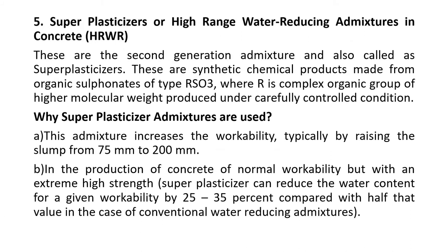Superplasticizers or high-range water-reducing admixtures in concrete. These are the second-generation admixtures, also called superplasticizers. These are synthetic chemical products made from organic sulfonates of type RSO3, where R is a complex organic group of higher molecular weight, produced under carefully controlled conditions.